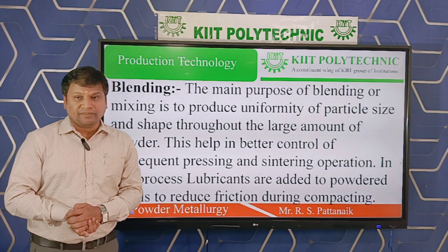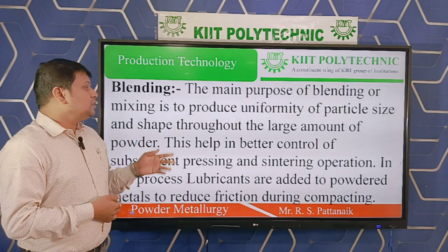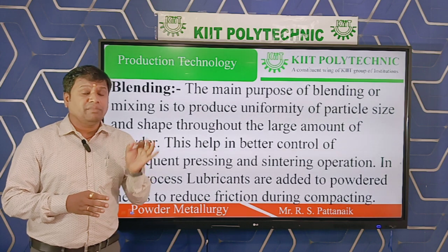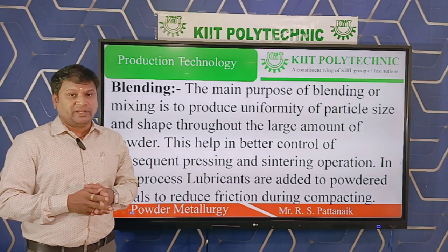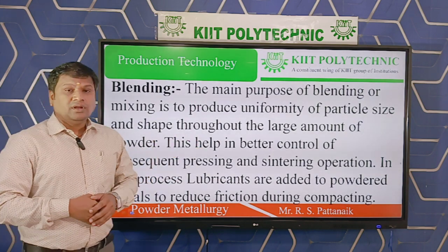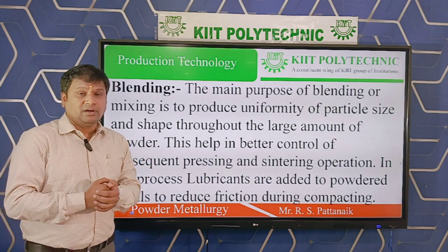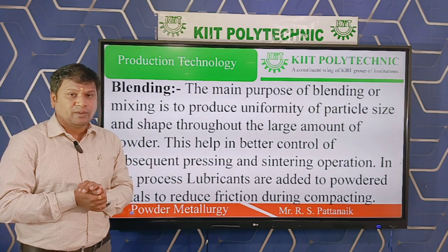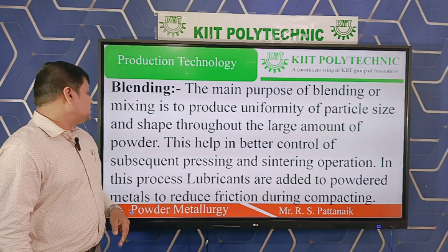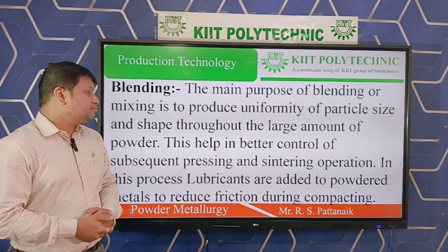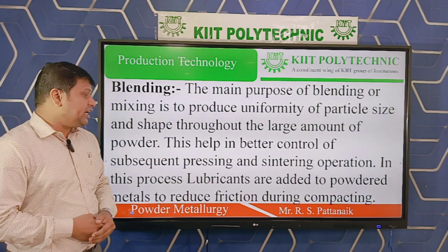The next step is blending, or we can say mixing. The main purpose of this step is to produce uniformity of particle size and shape throughout the large amount of powder. This helps in better control of subsequent pressing and sintering operations.